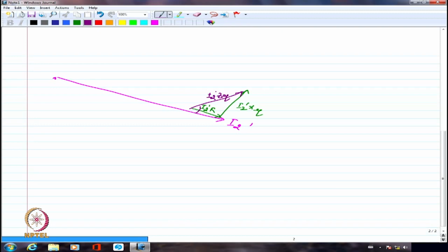We are neglecting it when finally we drew the voltage drop. We didn't neglect it initially. That's why we wrote very clearly IC, IM, sum of that is the no load current. Then that no load current we added to I2 dash and we said that was I1. But finally when I was writing the drop, I could have written I1 times R1, I1 times X1 plus I2 times R2, I2 times X2. All these things added together will give me the total voltage drop. But it is actually hair splitting. You don't really need so much of hair splitting.